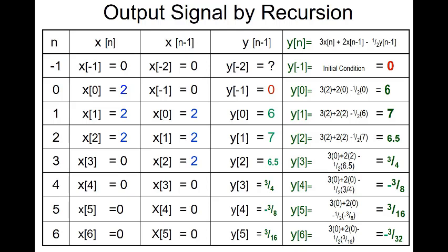And it's going to just keep feeding back that output. We're always going to have a term here. It's going to keep getting multiplied by a half and a minus. So every time it gets half as big, and then the minus sign just makes it oscillate back and forth, positive, negative, positive, negative, positive, negative, positive. And it keeps doing that forever. It never gets to zero. The transient response never dies out. Transient response is infinitely long. That doesn't sound good. Well, that's just the nature of that particular system.